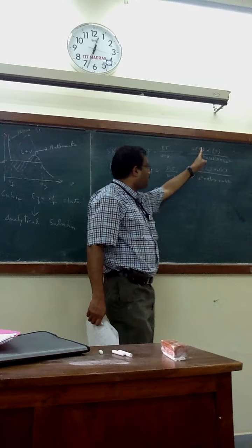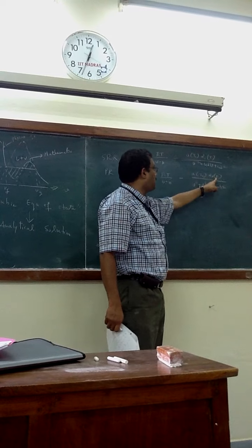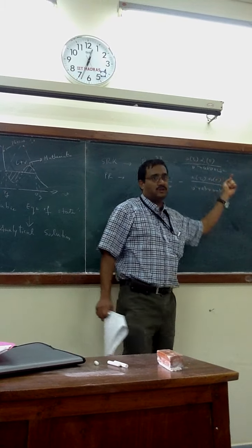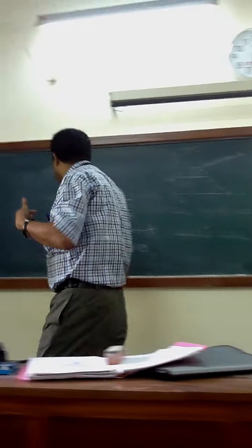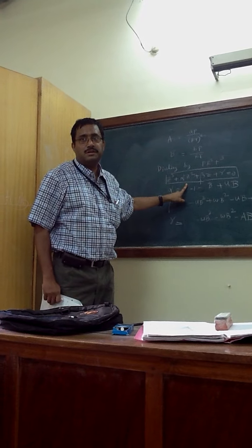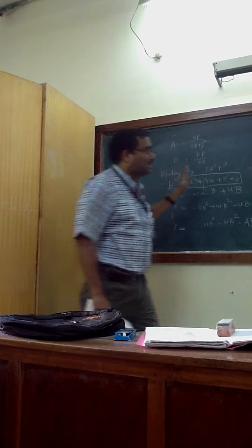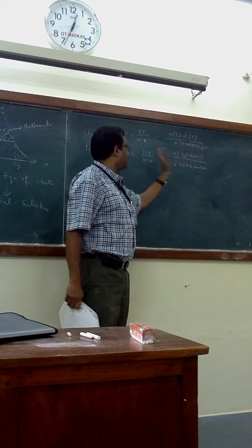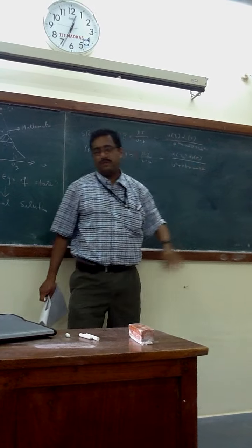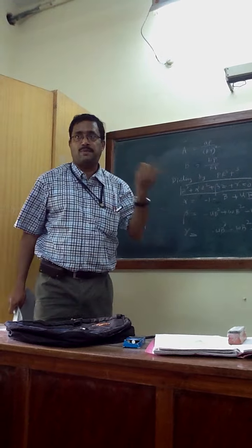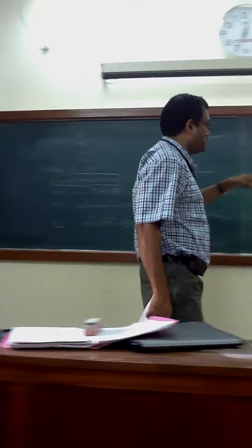So this term will contribute somewhere. Now you can see this alpha 1(T) and alpha 2(T) will be there somewhere in this term. There you have to be very careful because that's a function of temperature. At every temperature, this equation will change, the solution will change. Van der Waals equation is temperature independent, right? Of course temperature dependence is there, but it should not come here. This term is temperature free, right? This term is also very complicated for the SRK and RK, where temperature dependency is coming. In that A term, the interaction parameter has a temperature dependency. Earlier we had temperature dependency only via this term, but we have got complications here.